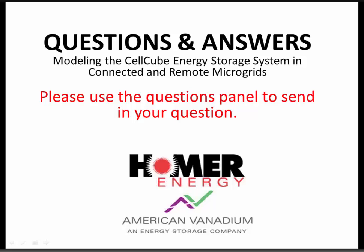And because, as I mentioned before, you can take these things down to 0 state of charge without any impact on life, the actual life of the battery is really determined by its age, not its performance. And so you would expect to see the membranes lasting around about those 20 years. And since that really is the important element of the cell stack, you would expect to see the cell stacks lasting for that length of time as well.